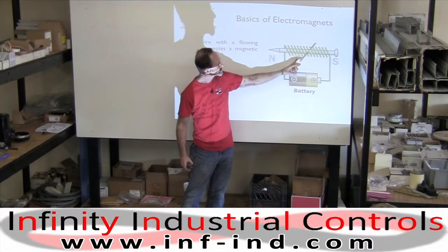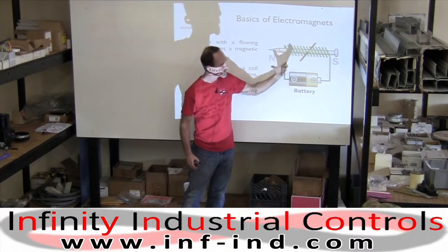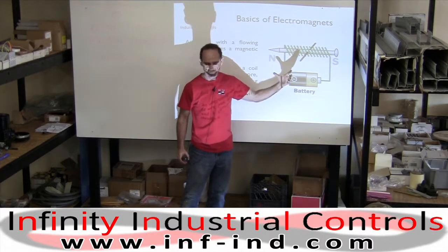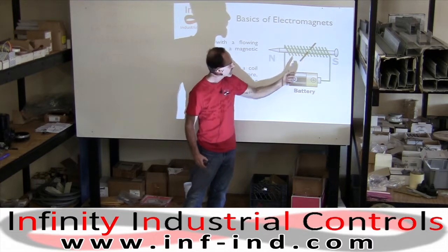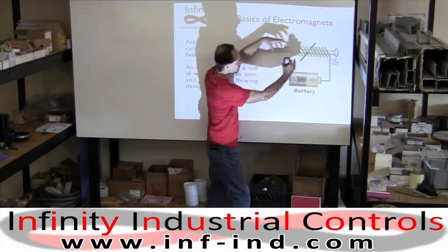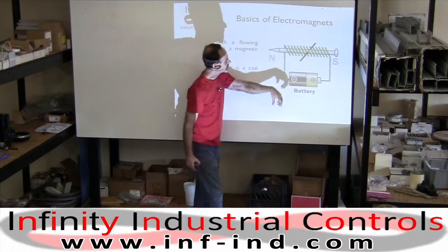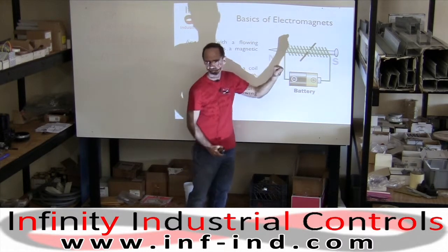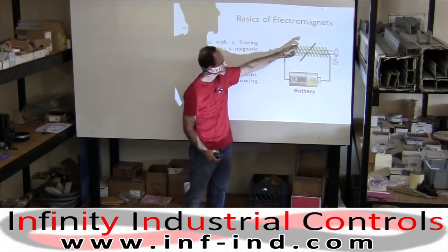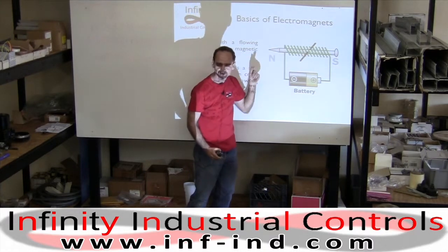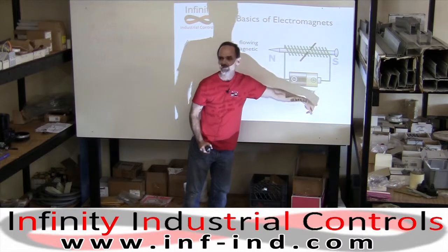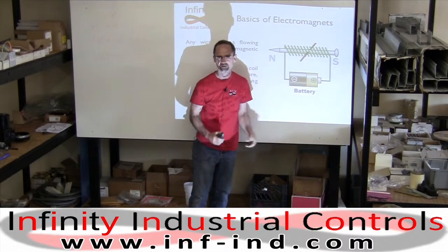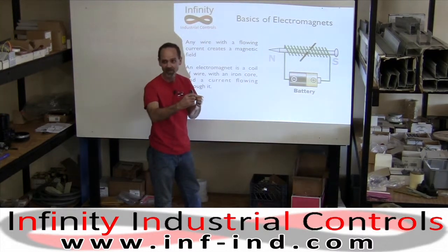One of the characteristics of these is that each one of these has that magnetic field around it, and once you energize this, it has an overall field. If you disconnect the power, that field collapses. And then as it crosses those metal windings, it induces a current in the other direction. It can be a very large spike. I don't know if anybody has ever done that. Disconnect the coil, make a pretty good arc.